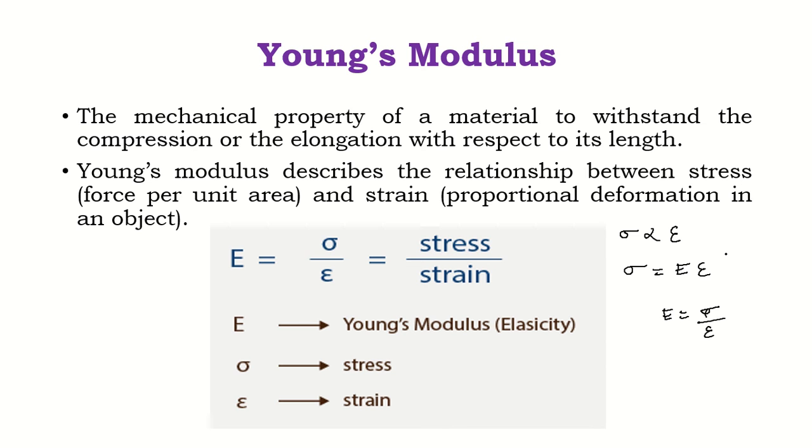So when any solid object deforms when a particular load is applied on it, if the object is elastic, of course the object will regain its original shape once you remove the load. Most of the materials are not linear and they are not elastic beyond a small amount of deformation. Hence, remember, Young's modulus applies only for linear elastic substances. You can see the formula, it is sigma by epsilon. Stress has the units of Newton per mm square because it's load by area. Strain doesn't have any unit, so indirectly stress and Young's modulus carry the same units.